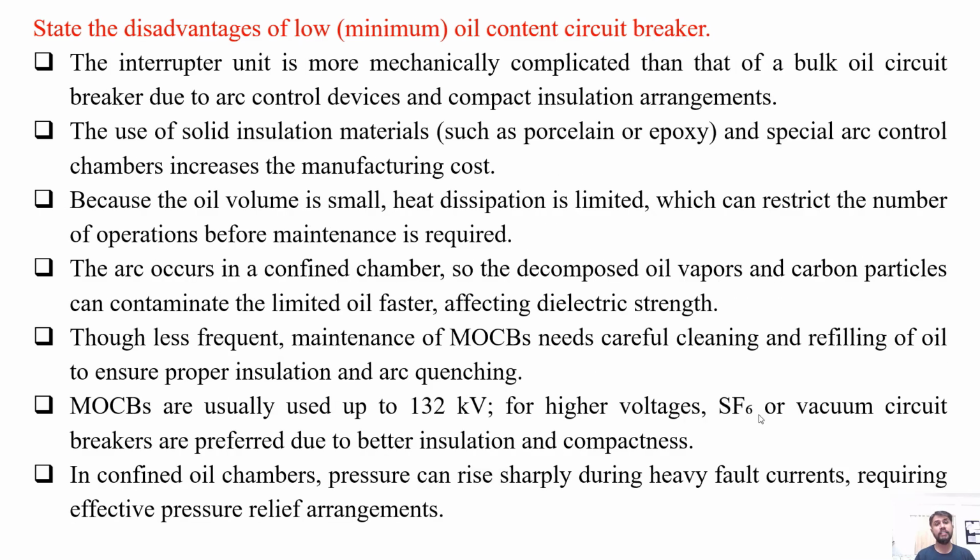State the disadvantages of low oil content circuit breaker, or say minimum oil content circuit breaker. So the interrupter unit is more mechanically complicated than that of a bulk oil circuit breaker due to the arc control devices and compact insulation arrangements. The use of solid insulation materials such as porcelain, epoxy, bakelite, etc. and special arc control chambers increases the manufacturing cost.